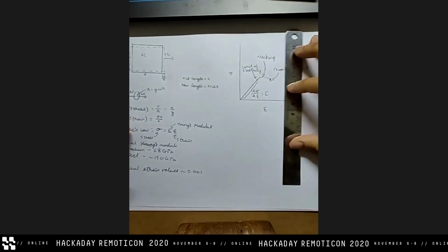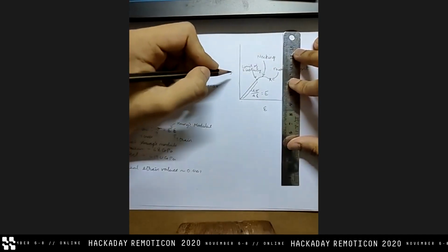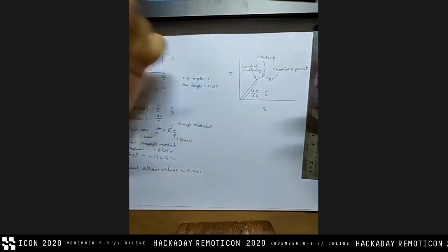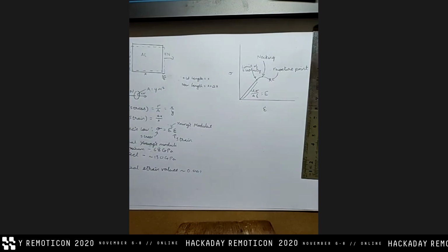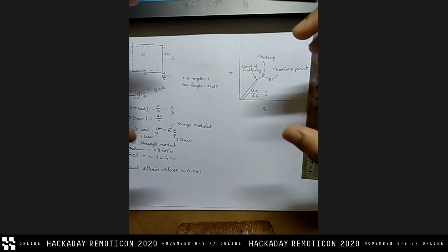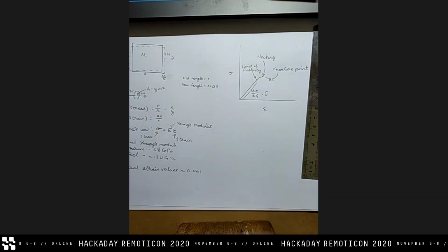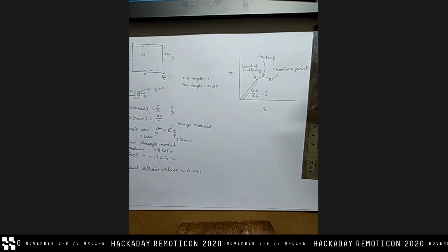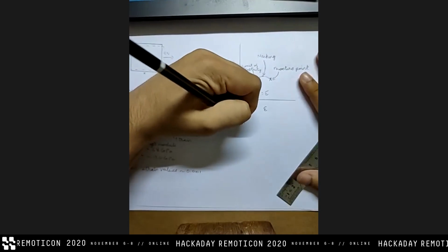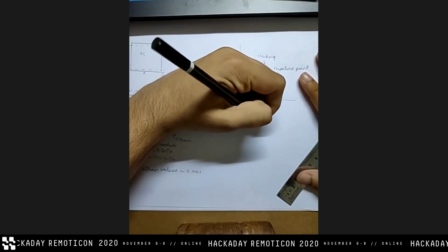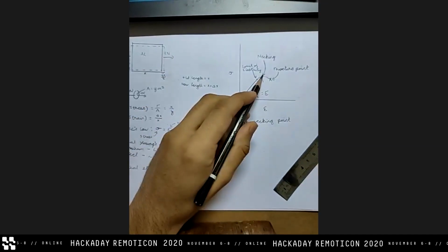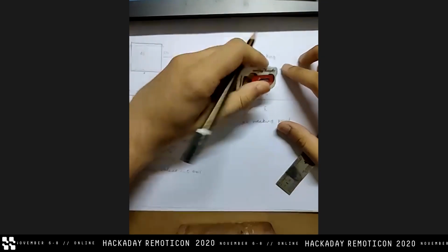What's interesting about necking is that this is called a stress strain curve, but what it actually measures is, let's say you have machines which can put a lot of tensile stress. The machine would actually be measuring the force, and you just divide it by the area to get the stress. So what actually happens at your necking point, because logically this really doesn't make sense.